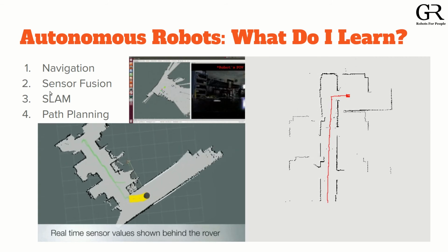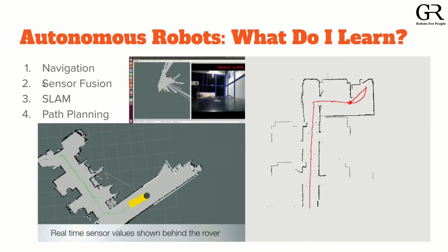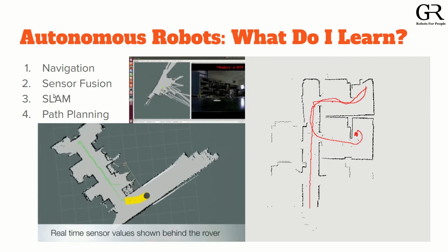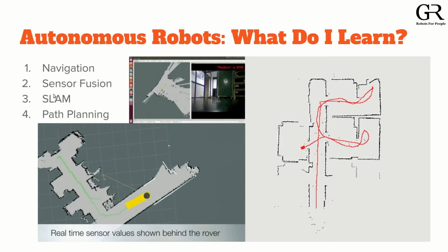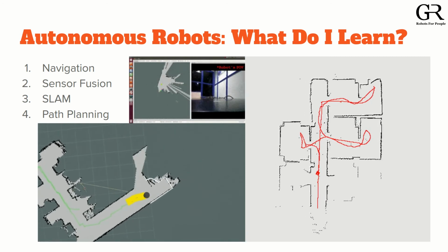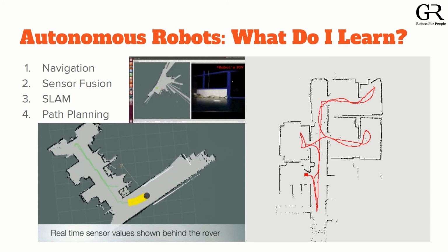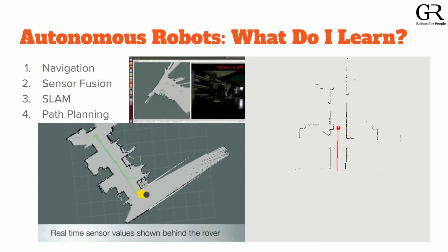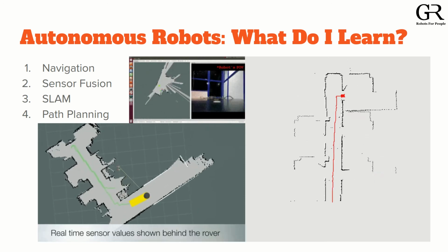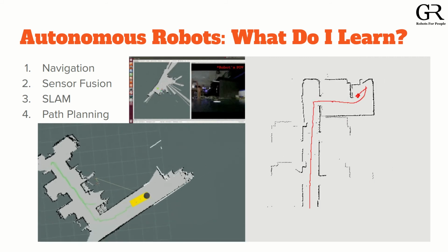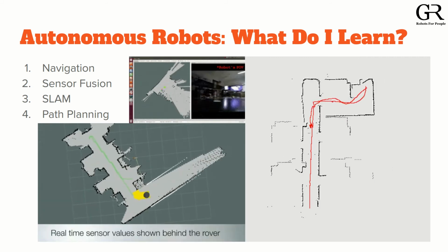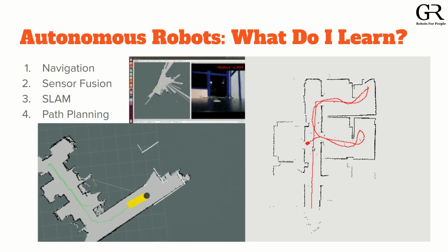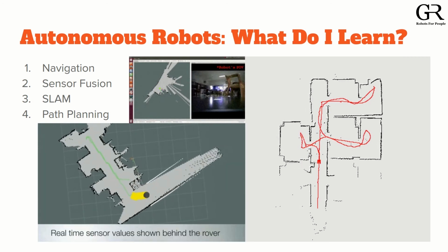SLAM is a more advanced thing in robotics. By doing that, you have to learn small concepts like filtering, Kalman filtering, or particle filtering. And you have to understand higher-end application aspects, such as exactly what ROS or any kind of socket based protocol is, so that your multiple nodes can communicate and process simultaneously, and it will create a map like this. You can see here, this small robot is creating a 2D map. This 2D map can be generated using a lidar sensor.